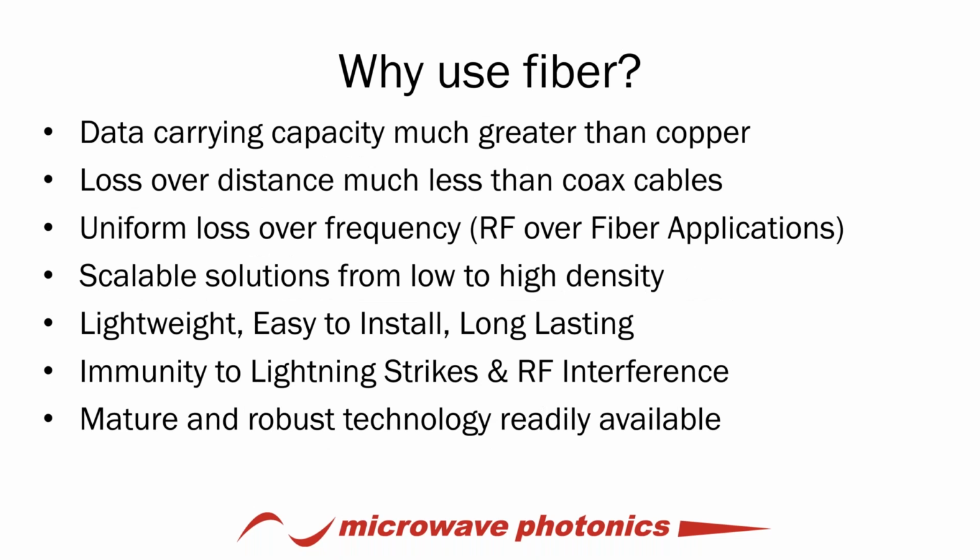And now the question would be, okay, well that's great that it's mature and it's robust, but why use fiber? Well, the answer is quite simple. First and foremost, the data carrying capacity is much greater than that of copper. And when you're designing a traditional coax-based system, one of the things that I've always struggled with, and it's going to be around as long as people are using coaxial cables and waveguides, is managing loss over frequency, and fiber offers a very unique characteristic that there is uniform loss over frequency.